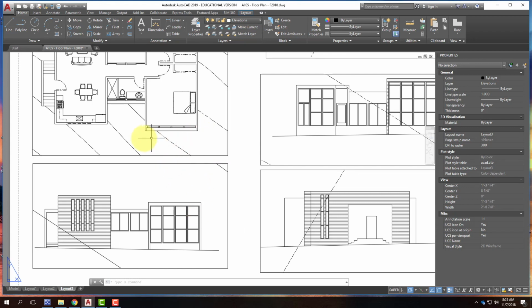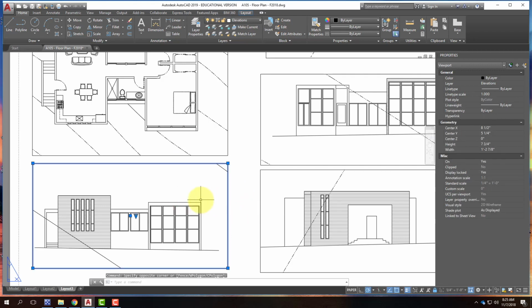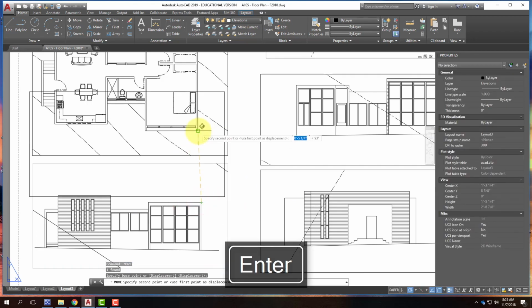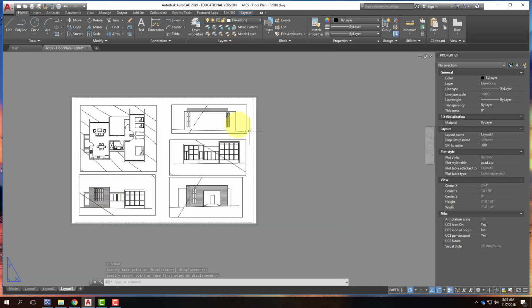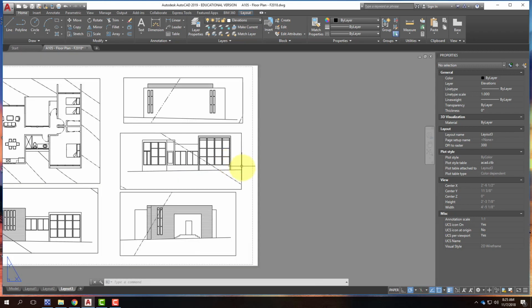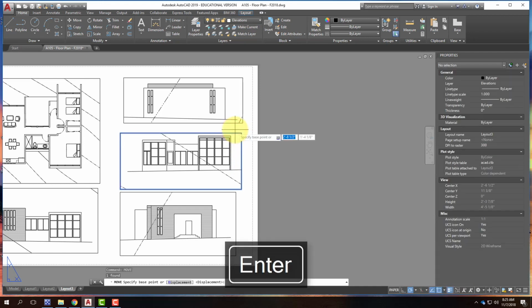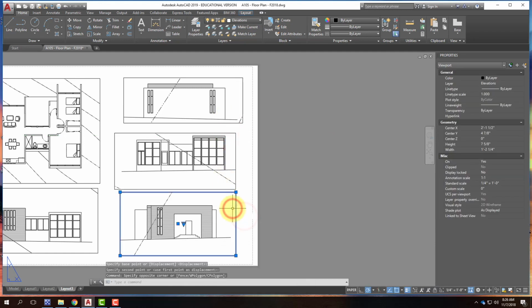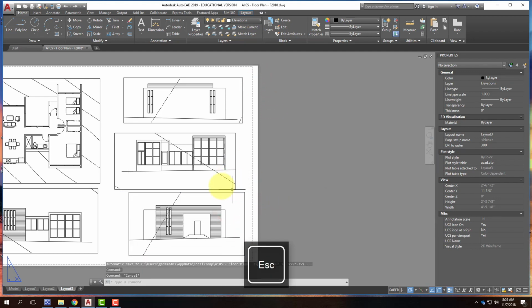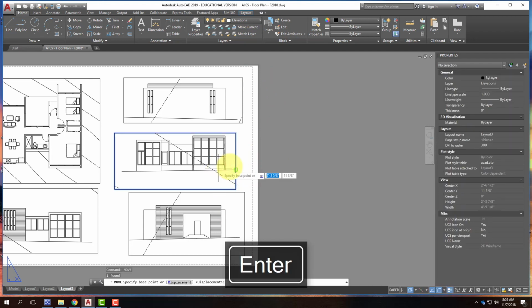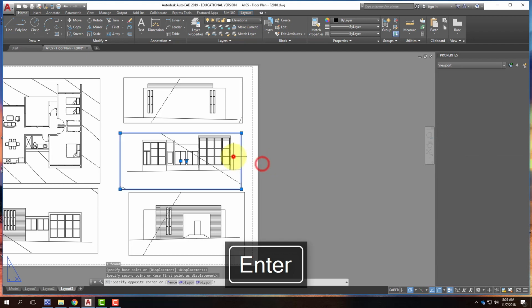So a couple things about alignments. Generally, when you set up these kinds of views, it's always important to have them such that they correspond up and down. So this view, for example, I just want to make sure that this corner matches up with that corner. So it looks like I need to move it over slightly so that everything lines up directly below. These views don't matter so much because they're all relatively independent, but sometimes it's helpful just to have one edge aligned. So I might move this one over to line up with that edge, and I might move this one over to kind of line up with that edge. Sometimes that helps. Sometimes you want to center them, in which case this one will get moved over a little bit more. Like that. Maybe that's a little too much.